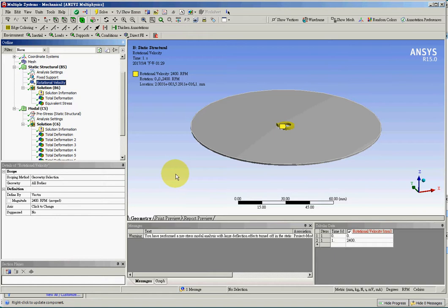So in this problem, it is very important to note that external force does not play a role in natural frequency or modal analysis. And only through pre-stress condition can an external load change the natural frequency of a structure.